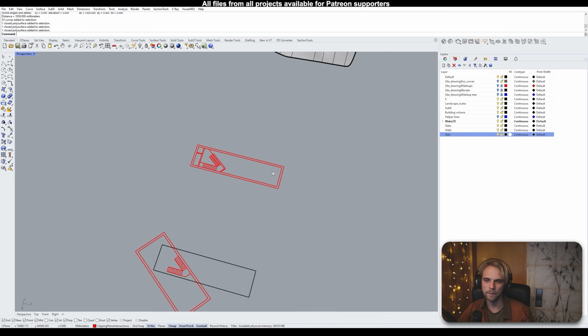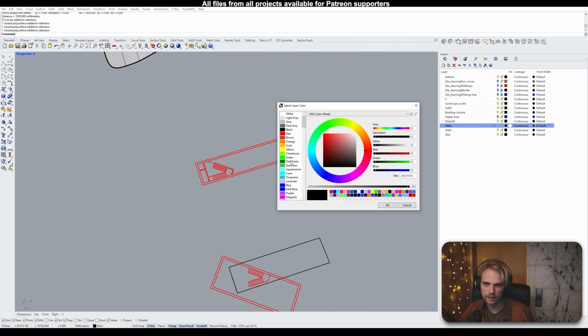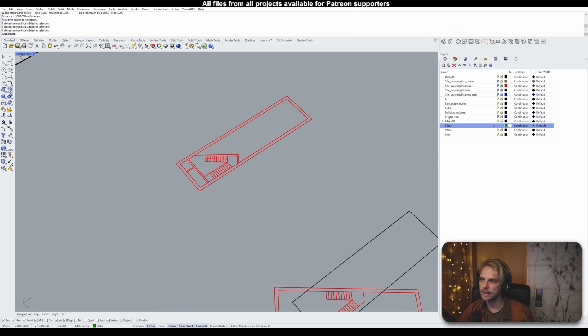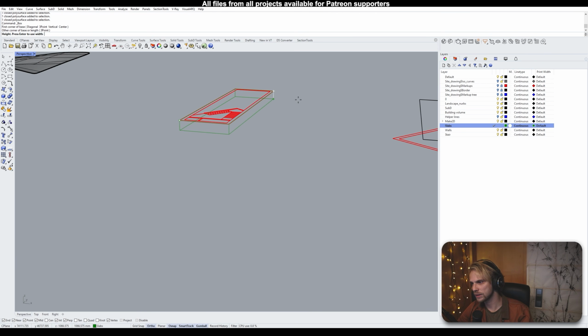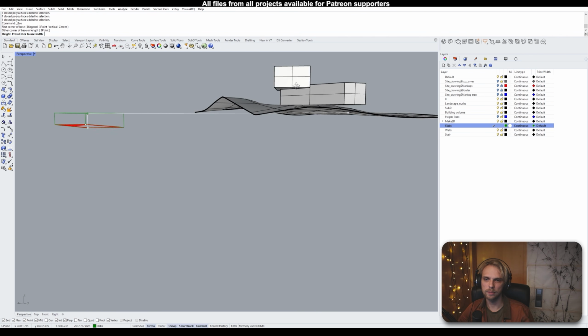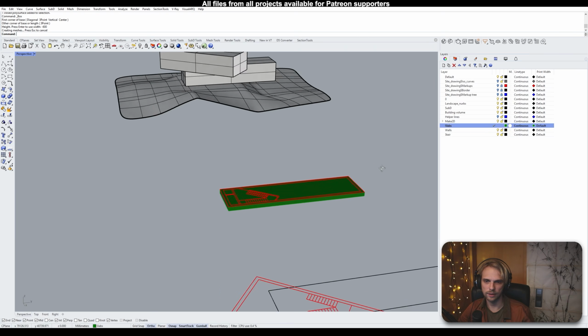and then we'll call it a day with the design of these two boxes overlapping. Alright, so in terms of creating slabs, I'll make it my active layer, and I'll make the slabs, let's say, dark green. I'll just make a box for the bottom slab right here, and I'll extrude it downwards by whatever the slab thickness should be. Since it is going to be a cantilever outwards, I believe the slab should be pretty thick. So let's go for 600 millimeters, minus 600, enter.